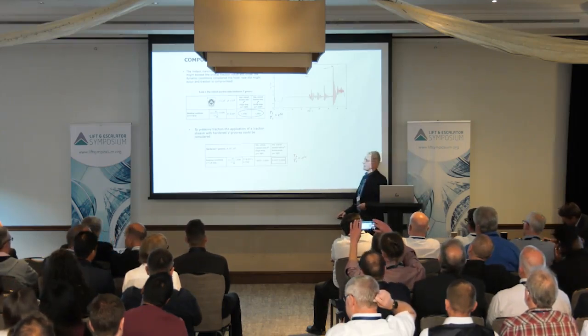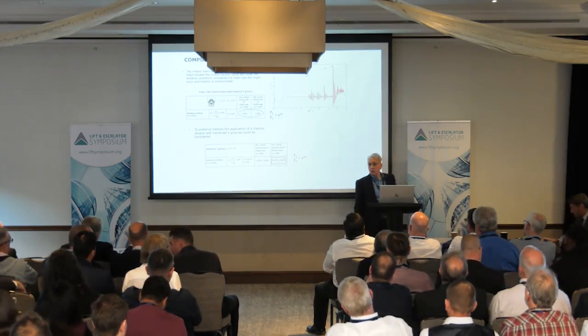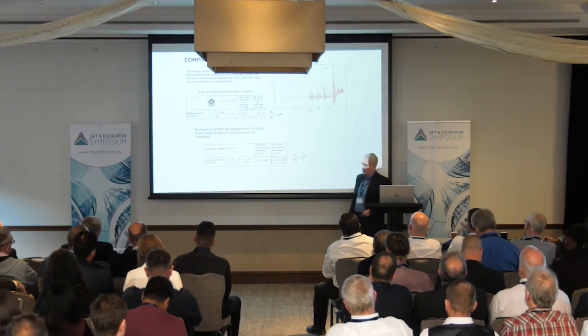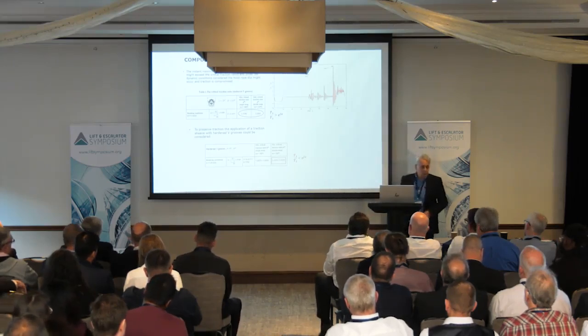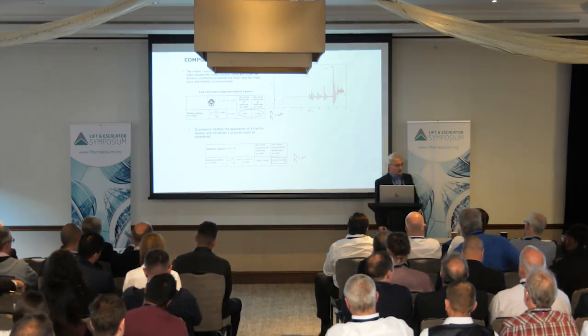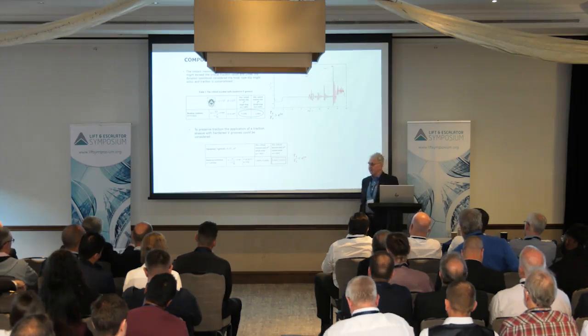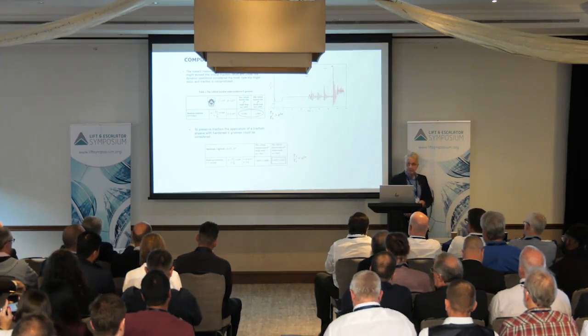So the cost is here, but when we replace the undercut U-groove with a hardened V-groove, it is the lifetime of the rope. We know that V-grooves can reduce the lifetime of the rope by up to 90%. So what next could be done?